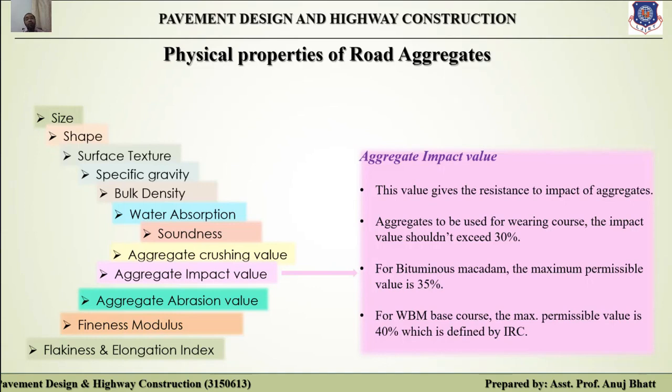The property of a material to resist impact is generally known as toughness, and that we can determine from this particular test, that is the aggregate impact value test.